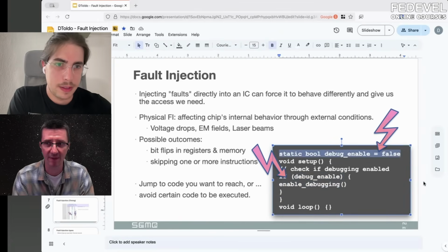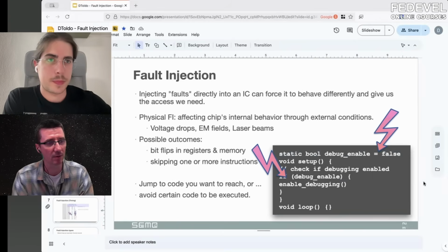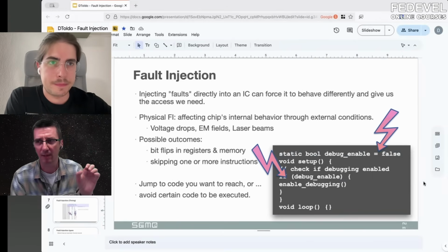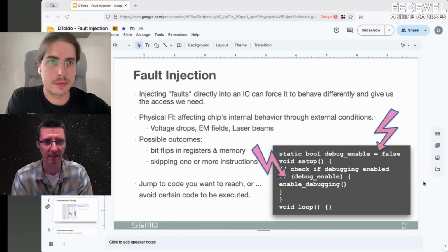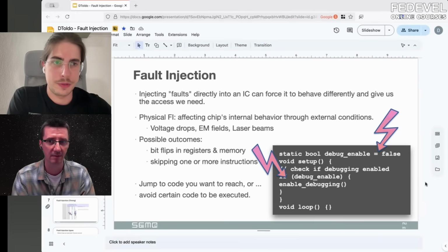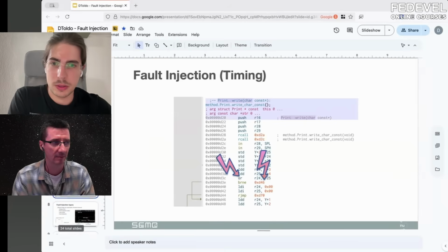Yeah, that's what I was thinking about because sometimes you can use the pragma, or how is it called? I don't remember, which will actually tell the compiler to remove pieces of code automatically if something is not set. That's correct. So if you use C macros, then you can mostly ensure that these parts will not be in the firmware.